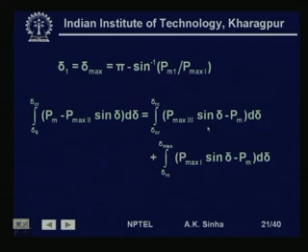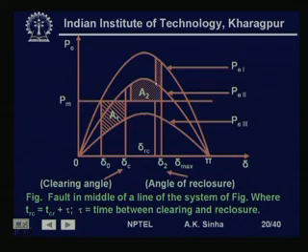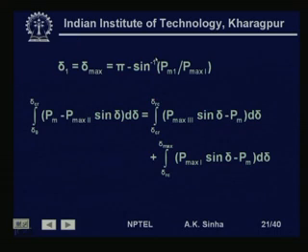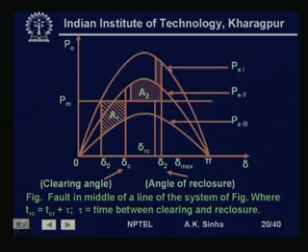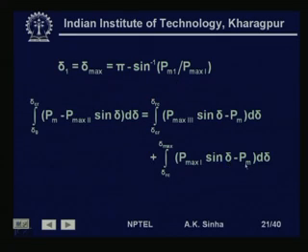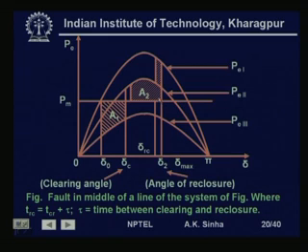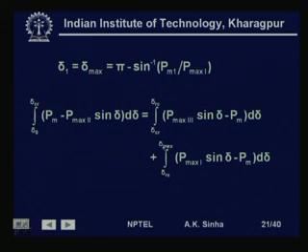This is the part that we get up to this point, that is this area, and from delta RC it jumps to this point. So, we have plus delta RC to delta max, P max 1 sin delta minus Pm, that is now the operating characteristics given by this. So, P max 1 into sin delta minus Pm minus this. So, from here this area will be available for deceleration. So, this area is what we are talking about here, delta CR to delta max.